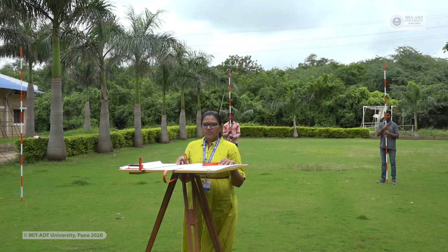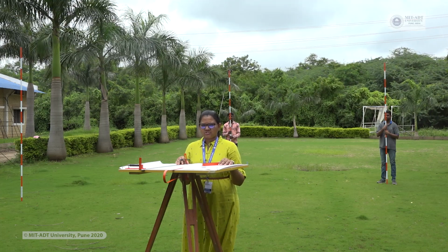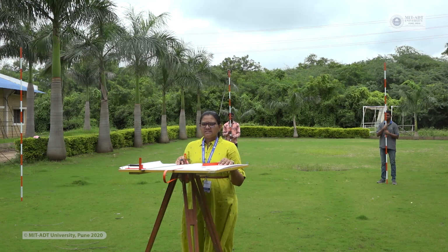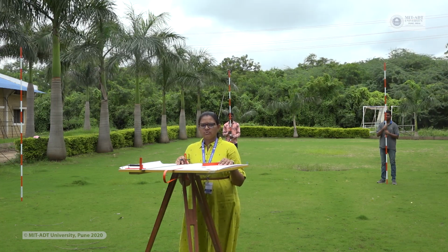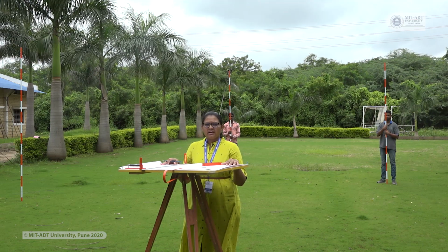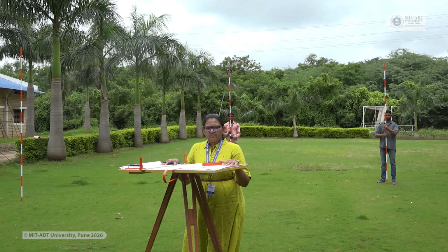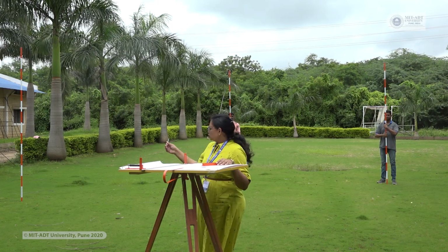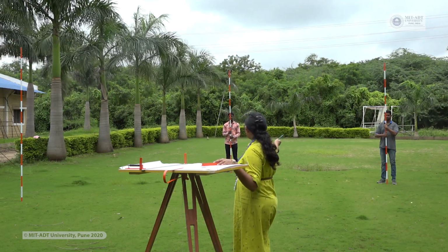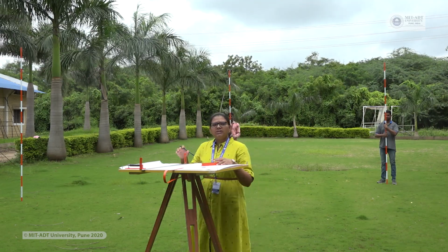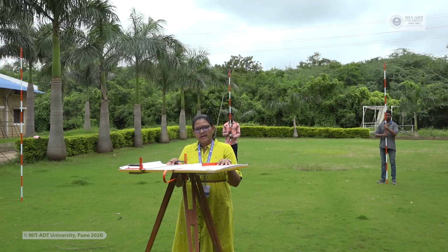So now we are going to perform this practical of plane table surveying by the method of intersection. In this method of intersection, we will need 2 points which we have to bisect, and we will need 2 station points. I am standing at the first station point, which is station P. This station P we have to mark, then station Q is there. Then we have 2 points, point A and point B. We have to mark the location of these points onto this paper by using the method of intersection.